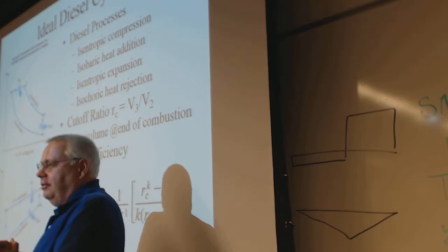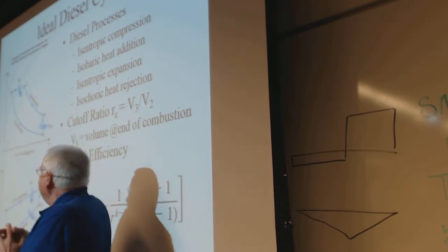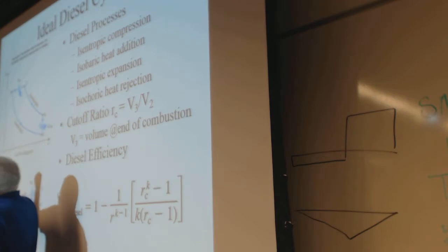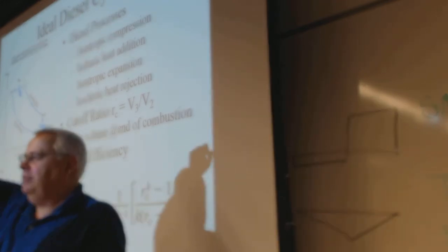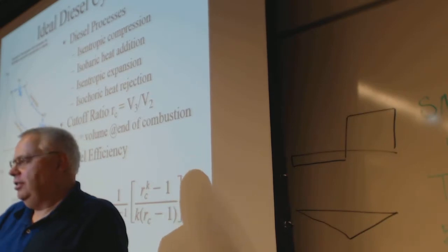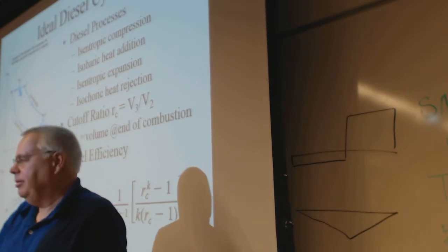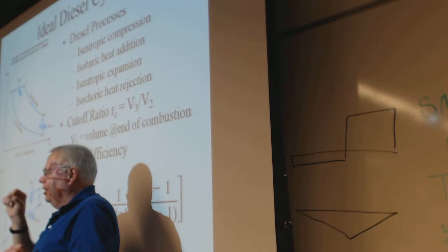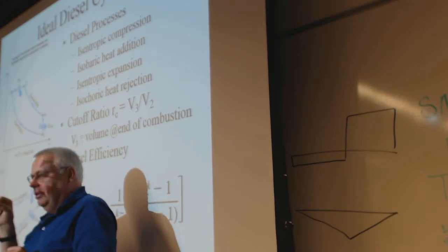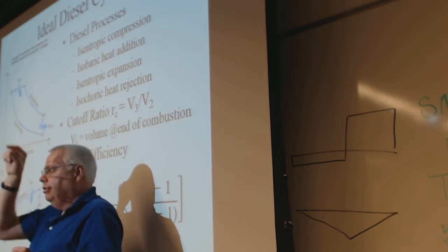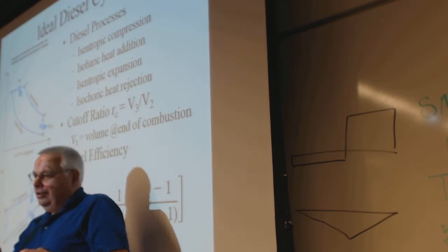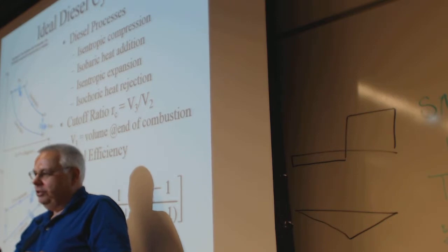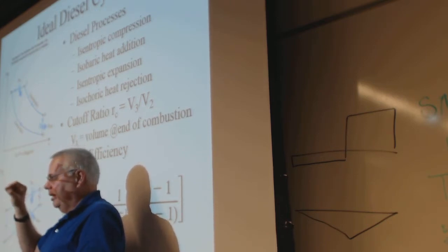Oh boy. So where was I? Same thing here on the steam tables. It's about looking at the table. Entropy at the top at one stage is the same value at the other for the isentropic, and I'll note that as the next state, well, not state 1 to 2s or state 3 to 4s or whatever it is. That's that calculated theoretical number, and then the real number it'll say like state 2a.